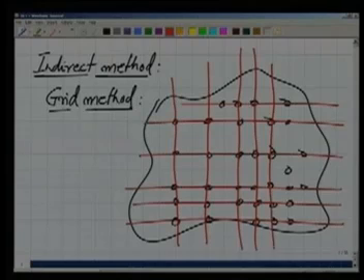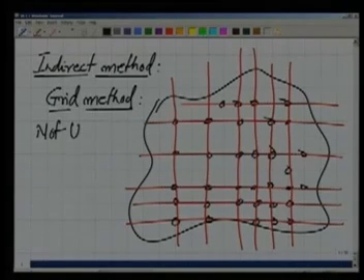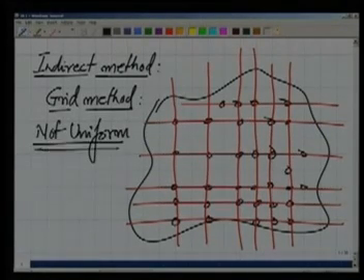However, at the same time you may be observing that the grid spacing is not uniform. It can be uniform or it can be non-uniform also. Whatever method we choose of planimetric survey, first of all we have to establish that grid, maybe by simple chains or by some sophistication, using theodolites.